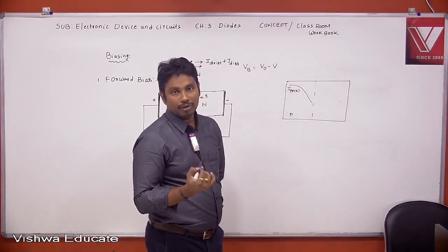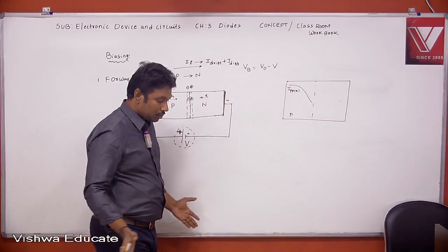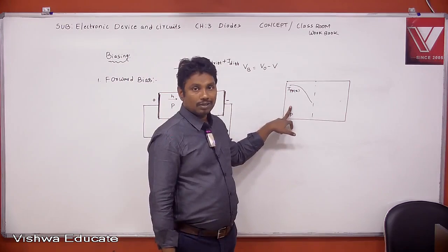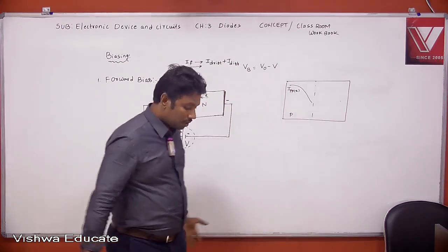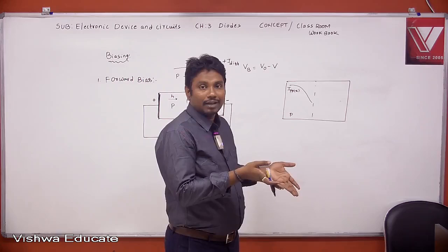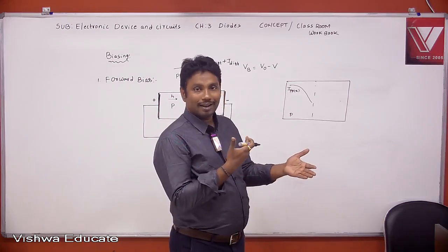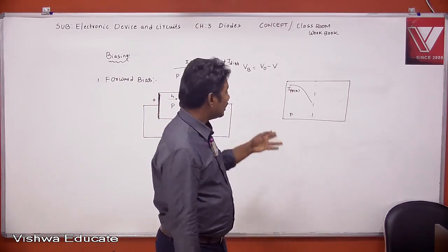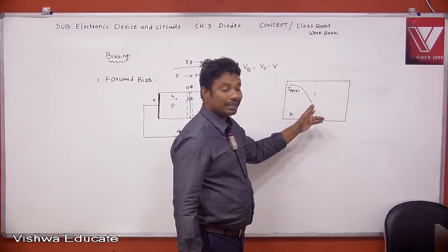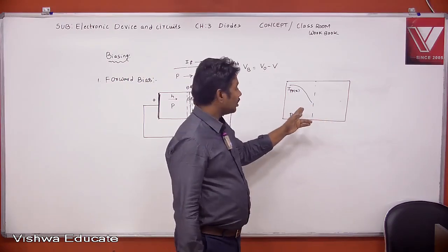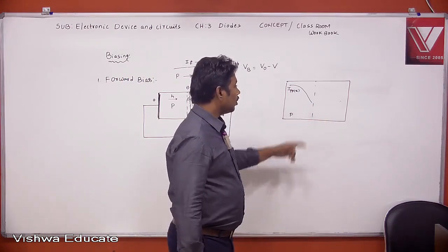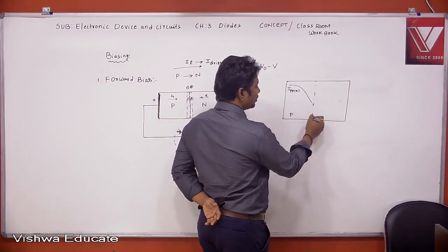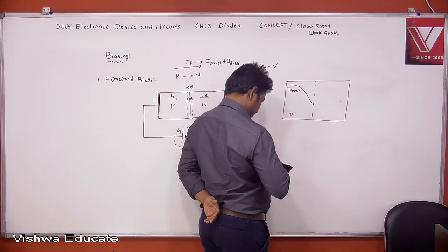Due to recombination, right? When the hole is moving toward the junction, in the meanwhile an electron will appear, because in p-type the majority are holes and the minority are electrons. Whenever the hole sees an electron, what happens? It will recombine and disappear, due to which this IPP of X starts decreasing. This IPP of X starts decreasing at the junction.